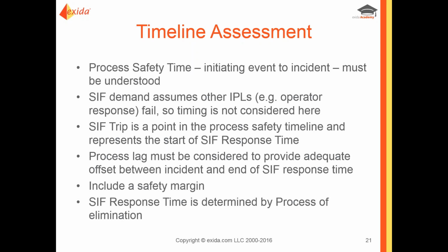For the SIF demand, we are going to assume that all other IPLs fail to respond, so we don't consider those timings there. Then we're also going to look at the SIF trip point as the beginning of that SIF response time. And then, of course, the end of the SIF response time is how quickly we want it to respond in order to achieve the safe state and turn around the escalation of the process.